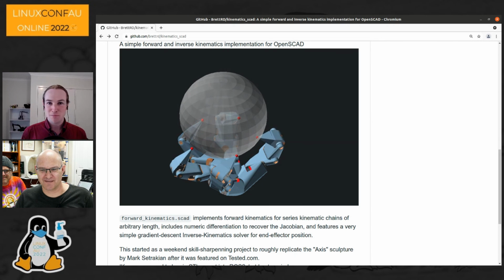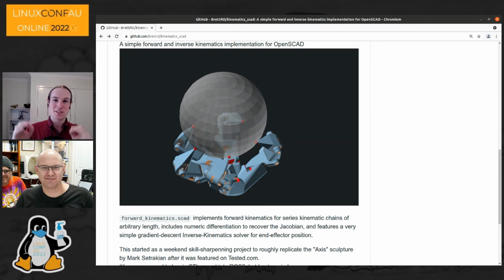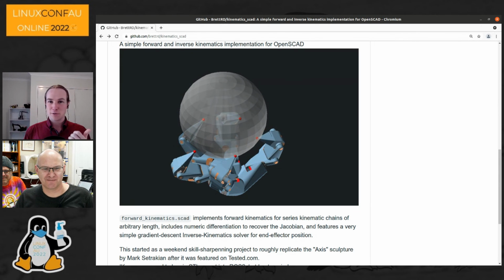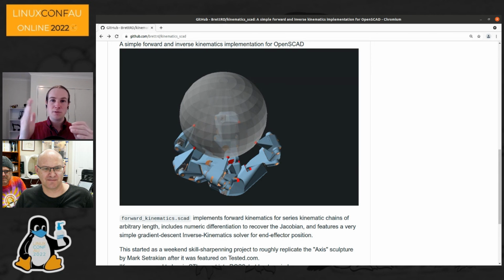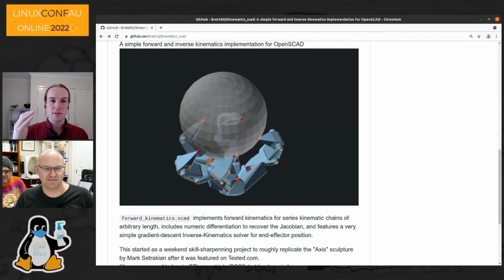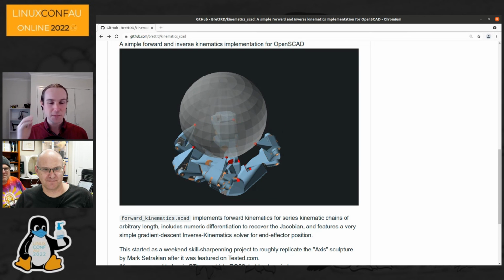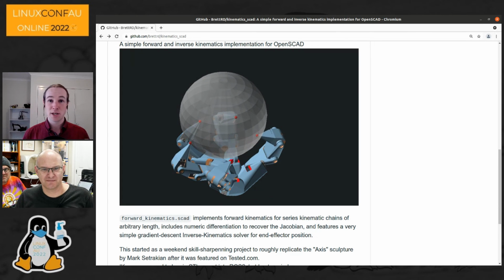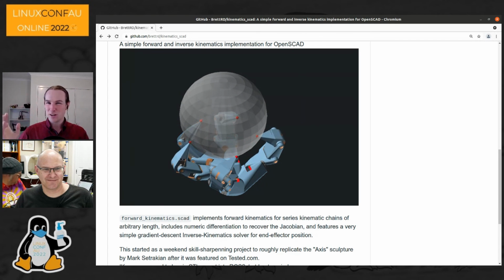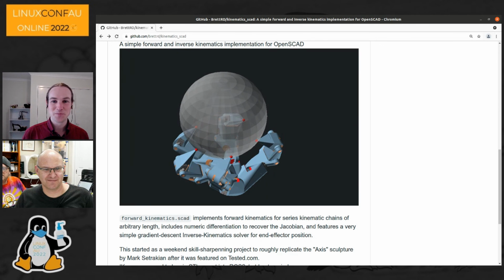I can't modify the control loop within the servo because it's an ASIC. It's just raw silicon. I find these are a bit squishy. If you move them from their target position, they just apply some torque to get back, but it feels a bit springy. So I had this thing rotating a salad bowl. It rotated, but it was noisy and rattly, and the contact points weren't actually where I wanted them to be.